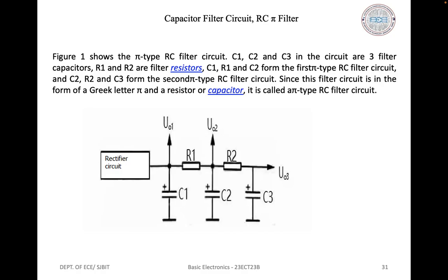Assuming a constant output load current, the reservoir capacitor continues to charge and discharge, producing a sawtooth or ripple waveform across C1 regardless of the presence of the additional components. Due to their higher frequencies, the harmonic components are more severely attenuated than the fundamental frequency component by the voltage division across R1 and C2.